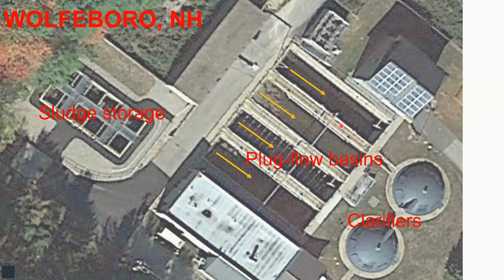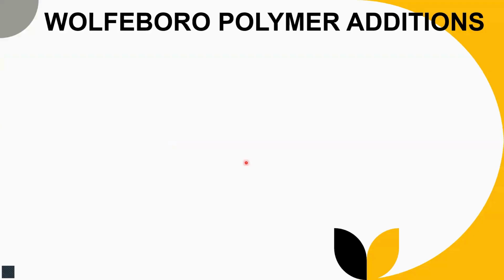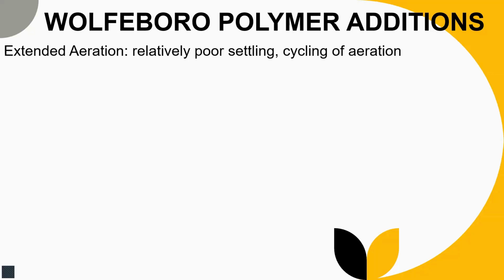So you have four parallel plug flow basins. Influent and RAS enter on this side, it goes over here, and then there's overflows to two final clarifiers. This is sludge storage. They haul liquid out of the plant. They're doing something really cool I'd never seen before, and I'm happy to get this out.